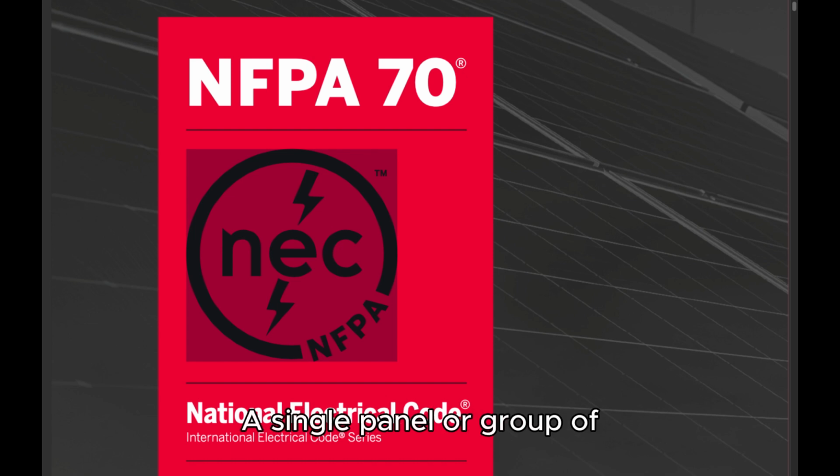CMP10 Panelboard. A single panel or group of panel units designed for assembly in the form of a single panel, including buses and automatic overcurrent devices, and equipped with or without switches for the control of light, heat, or power circuits, designed to be placed in a cabinet or cutout box placed in or against a wall, partition, or other support, and accessible only from the front.